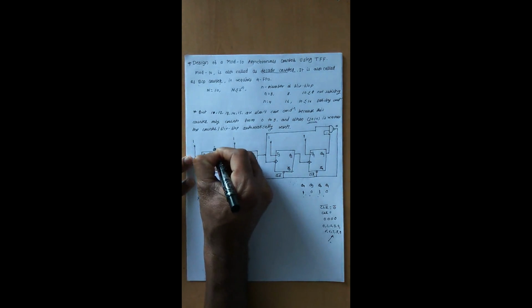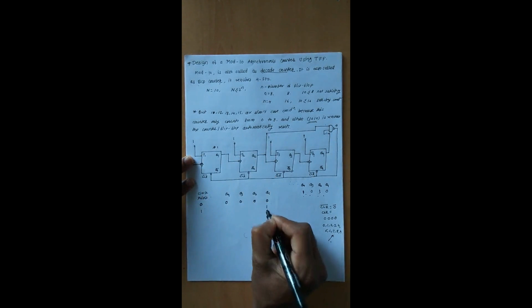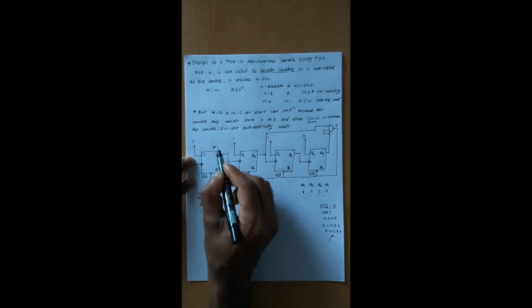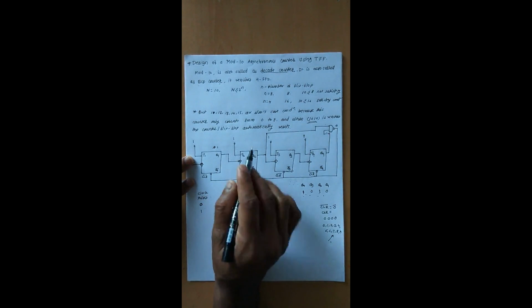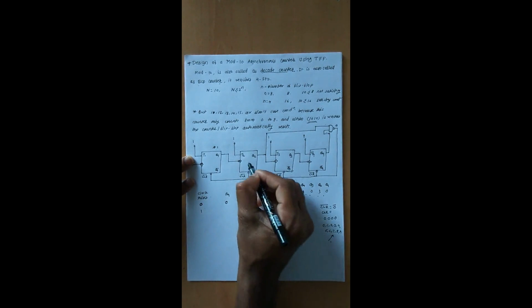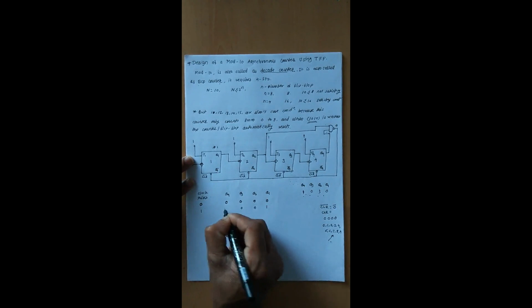This initial value is 0. Due to toggling, it will be changed, it will be 1. This 1 is given to the bubble, so it is converted into 0. So flip-flop 2, flip-flop 3 and flip-flop 4 are in the off state. So the contents of the outputs of all the flip-flops are not going to be changed.